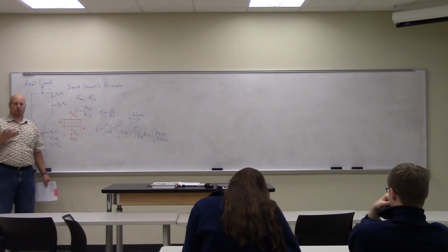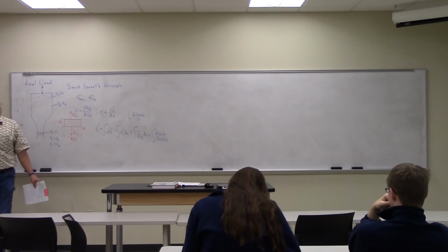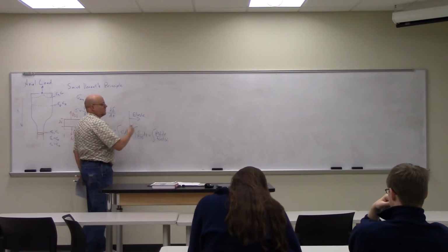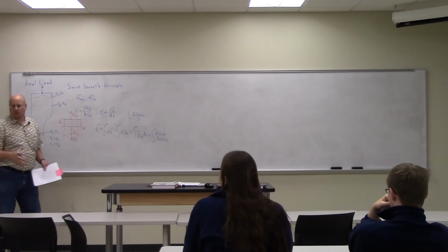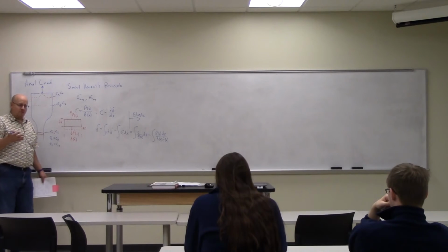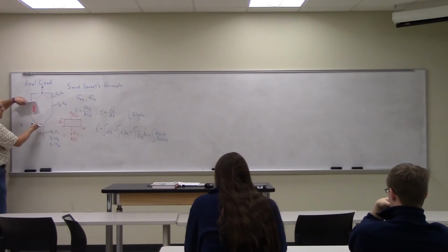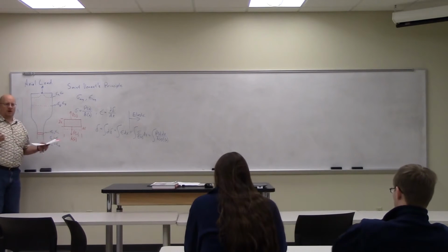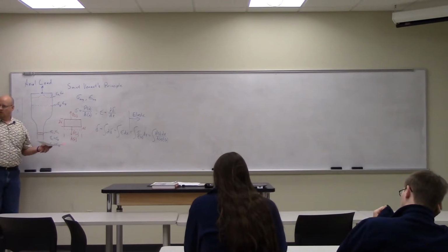So I have three things that vary as a function of position, and I would have to integrate those three functions. Now obviously that's going to be kind of ugly. If we really had this load distribution and the area changes, all some kind of functional behavior, we'd have this big ugly integral. But in reality, most of the time, there will be sections over which those things are constant. Or at the very least, over which P of x varies, but A and E don't.